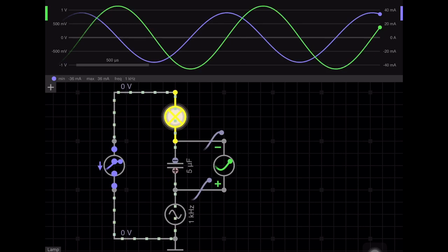The resultant voltage will be equal to the voltage across the capacitor in a pure capacitive network. But this is not a pure capacitive network, this is an RC network. So the voltage across the capacitor and the current flowing through it will have a 90 degree phase difference, but the resultant voltage as well as the current will not have a 90 degree phase difference.